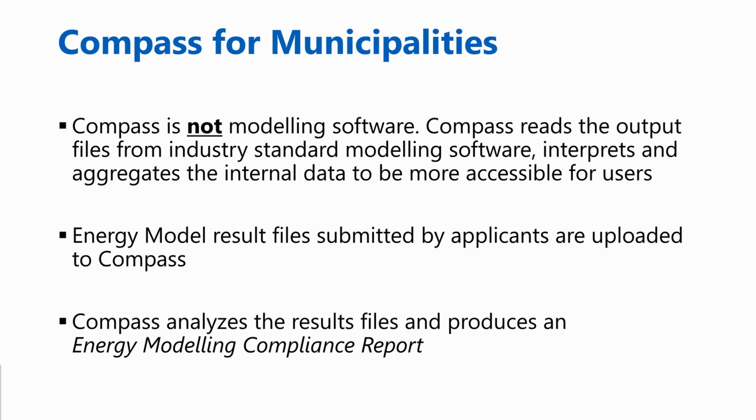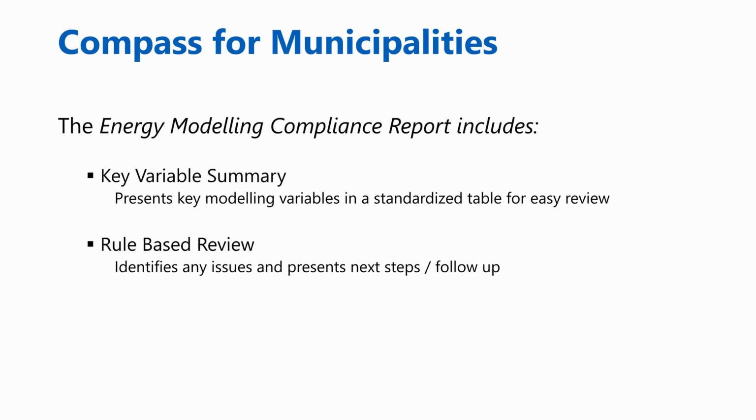Compass is not energy modeling software. Compass reads the output files from industry-standard modeling software, interprets and aggregates the internal data to be more accessible for users. The energy model result files submitted by applicants are uploaded to Compass. Compass analyzes the results files and produces an energy modeling compliance report. The energy modeling compliance report includes two key components, the key variable summary and the rule-based review.